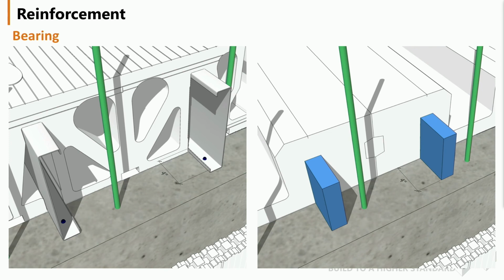Since the wood joists could be non-treated lumber, the ends need to be protected from the direct contact of the concrete. The wood ends can be wrapped in 6mm poly, or self-adhesive waterproofing membrane, or self-adhesive flashing membrane, something that is water and vapor proof to make sure it doesn't rot over time.